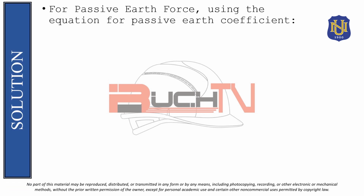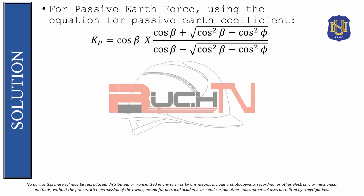So, if we were going to solve for the passive earth coefficient using the Rankine sloping backfill equation, we will have K sub P is equal to cosine beta times cosine beta plus square root of cosine squared beta minus cosine squared of phi, divided by cosine of beta minus square root of cosine squared beta minus cosine squared of phi.